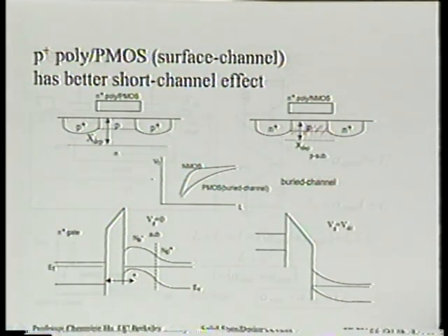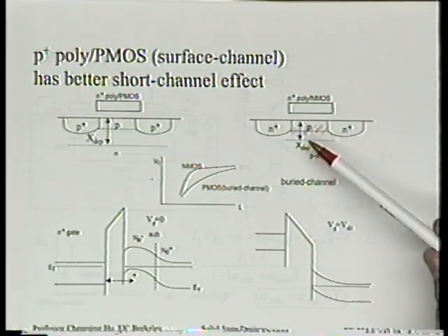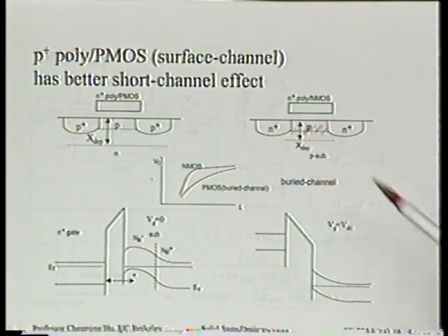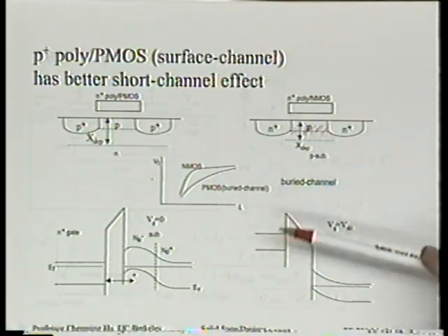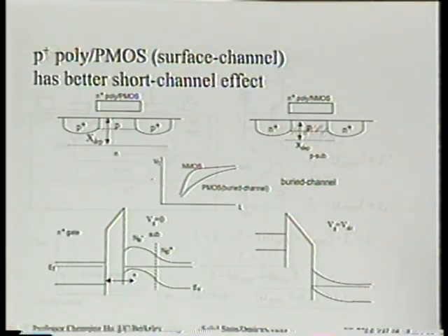Remember that exercise? All right. We can get the same VT, but having half the depletion region width, comparing the ideal retrograde design and a uniform design. Okay, that's the basic benefit.